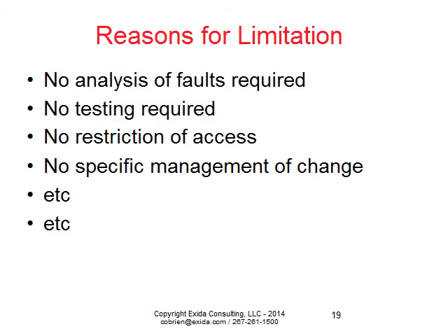The reason is, to do that, there's no analysis of faults required. There's no testing required. There's no restriction to access of either the gas detector or the PLC or the valving required. There's no specific change management required. There's nothing really different than a general loop required. And because of that, you don't have to put that overhead in there, but you also can't claim higher risk reduction.